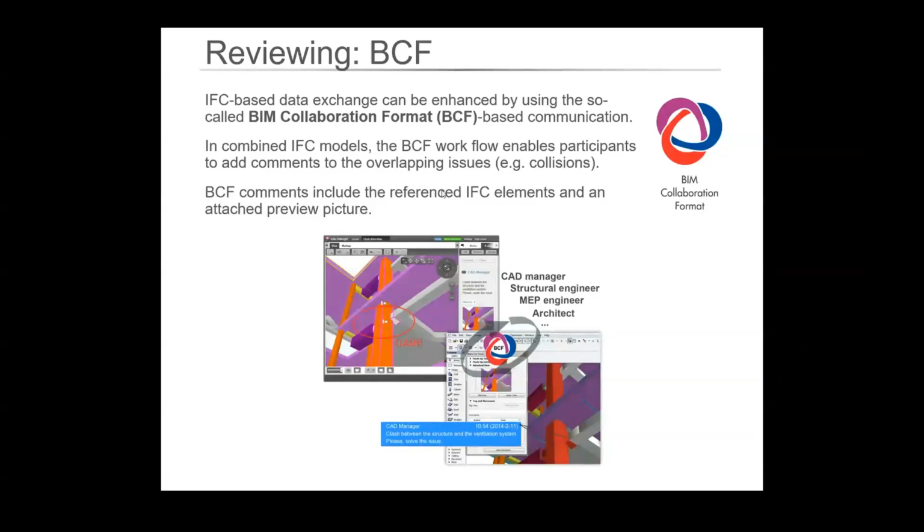And then you export that in your BCF format, and all that information goes with it and can be opened up by someone else, and they can see all that and mark it off. If you're using something like BIM Collab, where it's all done quite seamlessly, it'll go back to the web, and once you've clicked that you've done it, it'll show that it's been resolved by someone at a certain time.